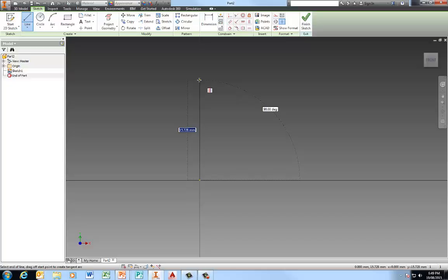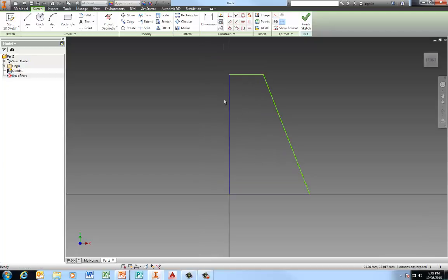The vertical height that we want here is going to end up being 80 millimeters, but for the moment I'm simply going to sketch the approximate outline. So here you can see what is essentially the right hand side of our front view. The central axis line is the horizontal line here on the left of the profile, and that's the line about which this profile will end up being revolved.